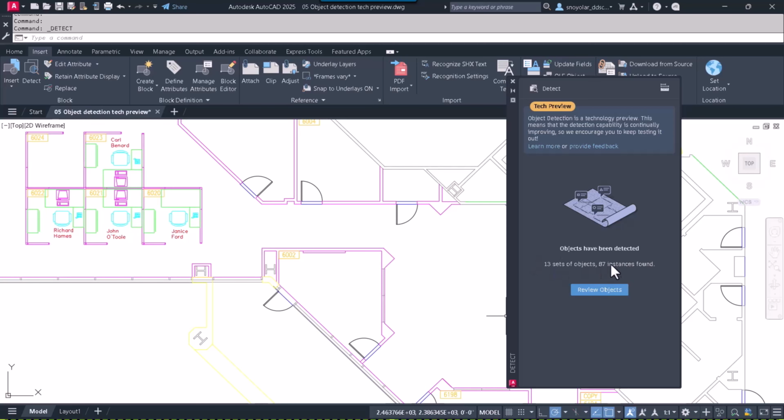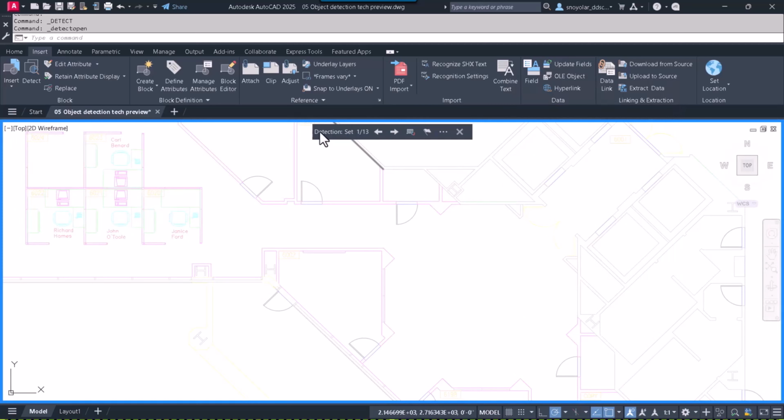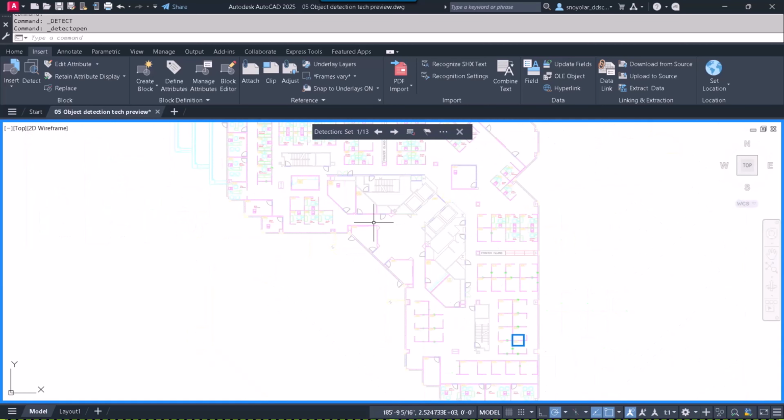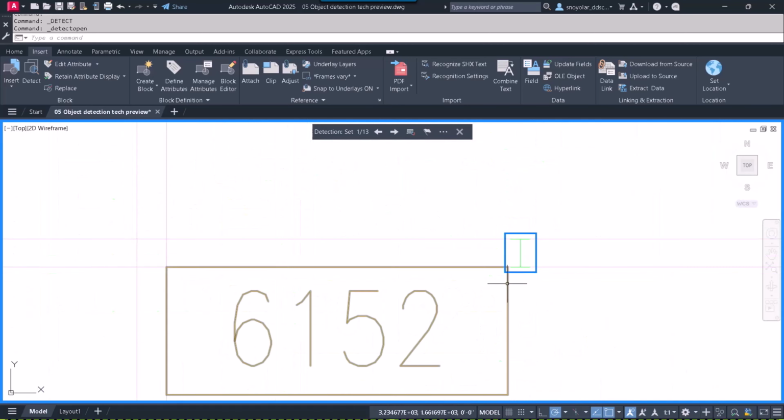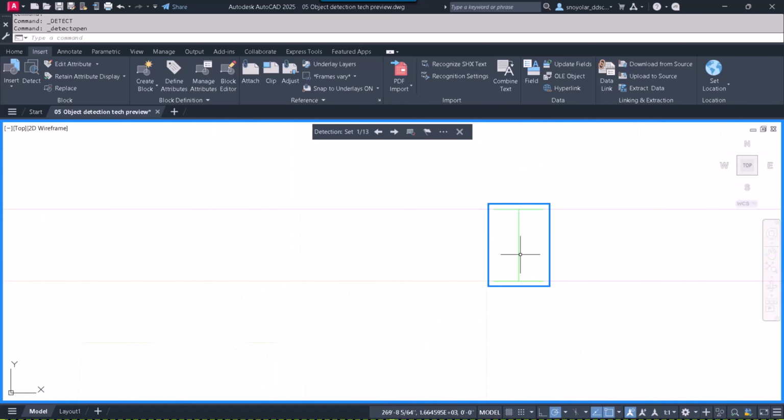When you activate the Review button, it shows us this toolbar that you see on the screen. It is the navigation bar to convert to blocks, detect errors or report errors, and to be able to determine which instance will be the main one and remove instances in that recognition set. And let's analyze what it found. It found here an element that could be a structural profile.